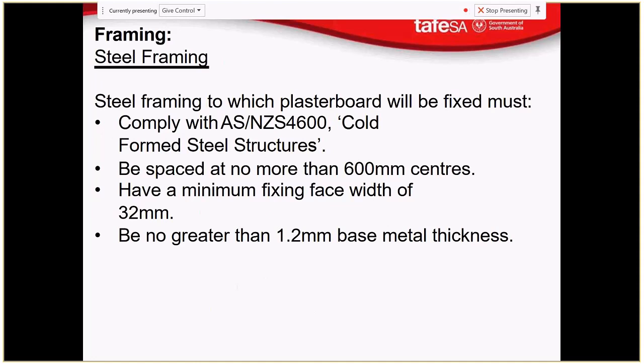Yeah, fixings. When you exceed 1.5mm or 1.2mm base metal thickness, you can have tek screws with metal heads that will drive into 3 or 4mm steel, but it is not easy. You have to be providing a lot of pressure, and then it goes. So you want to have a thinner, lighter gauge steel, so you can fix in quite easily.